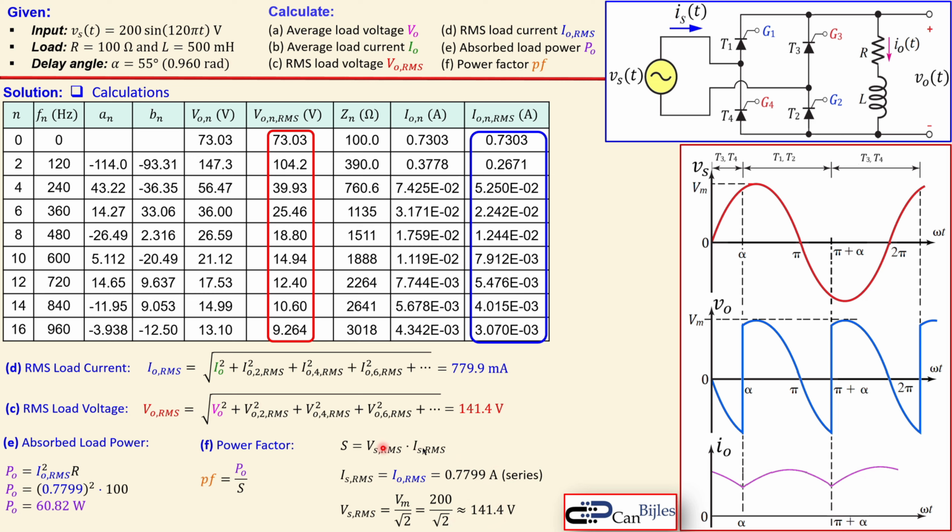Now taking this together in this formula, multiplying that, you get 110.3 volt-amperes. That is then substituted using also the value from question E, and you get a power factor of approximately 0.55.